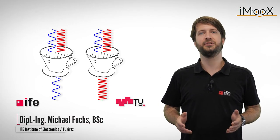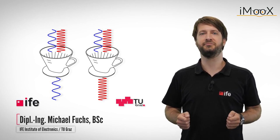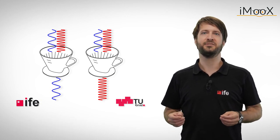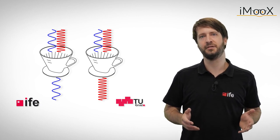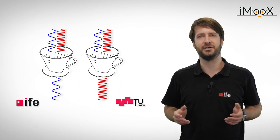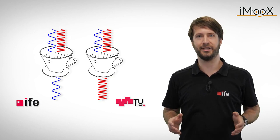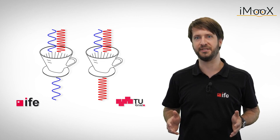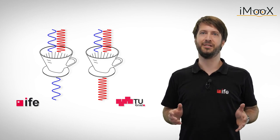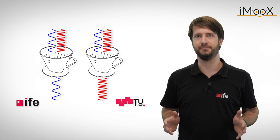In our last video, we discussed one of the simplest filters used in electronics, a passive first-order RC filter. This filter can attenuate high-frequency AC signals while it passes through low-frequency AC signals. As we have already seen, this little circuit does the trick in principle, but its behavior is far from ideal. A major problem is the unsatisfying decrease of attenuation for signal frequencies above the corner frequency. Fortunately, there are quite a number of solutions for this problem, which all have their strengths and weaknesses. So let's take a look at some of the more elegant filter circuits and their application.